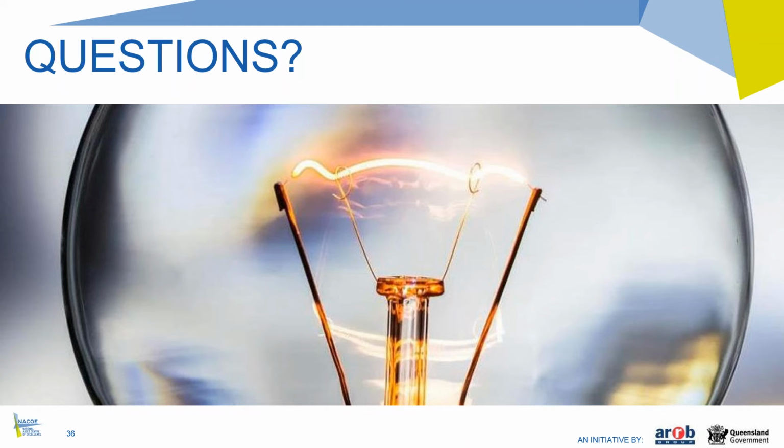Peter, actually, I got a question. So when we come to making the two Circly runs here, using the 53 kilonewton and the 80 kilonewton, given that we are going to linearly scale everything to the different load levels, 10, 20, 30, are there rooms to simplify? Rather than using 53, use 50 kilonewton in the calculation?